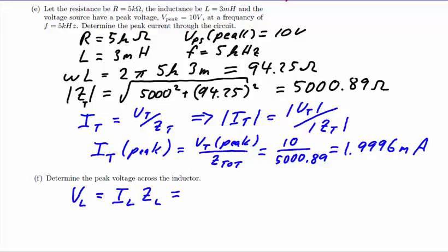Because we have formulated a series circuit, the current through the resistor and the current through the inductor are the same as each other and are the same as the total current through the entire circuit. This expression of full quantities that contain both magnitude and phase can be broken down into the portion concerning only the magnitudes, and we recognize that this expression will be correct if both the voltage and current are expressed as peak, or if both the voltage and the current are expressed as RMS.